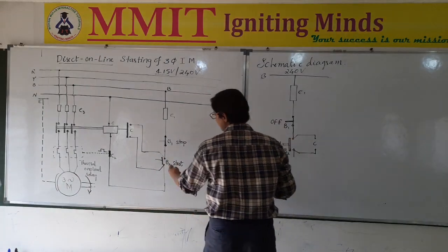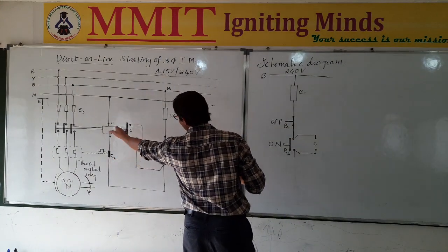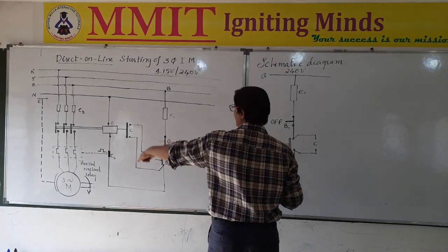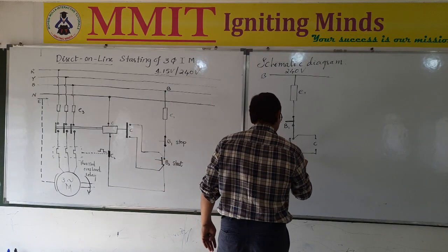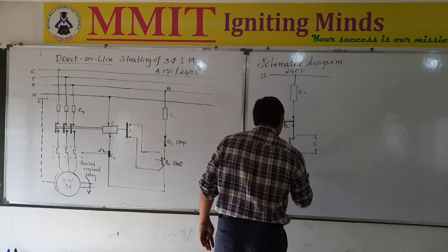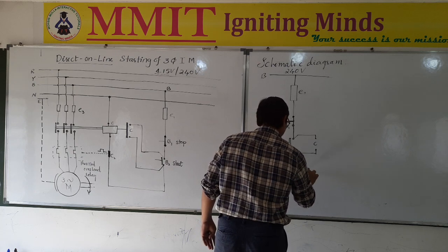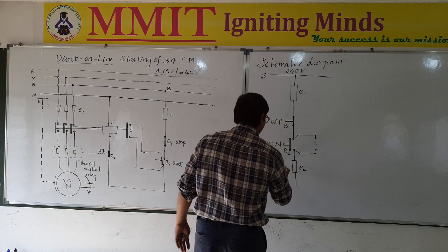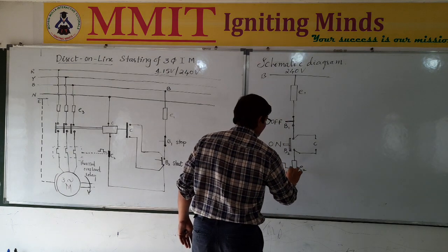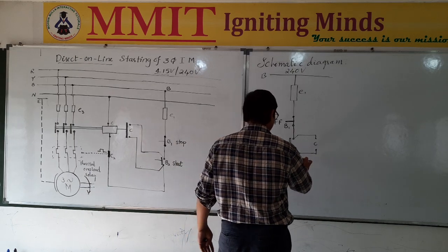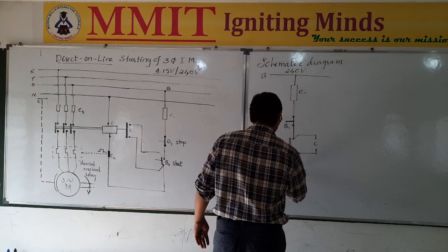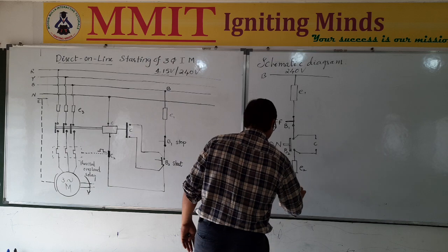That connection will go through first the fuse E2, and then it will go to the contactor C, and it will be connected to the neutral point. Now this fuse E2 is going to be operated from the signal coming from the thermal overload relay. In that case only it is going to operate; otherwise, in normal condition, it will always be closed.